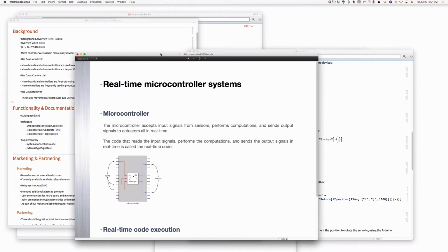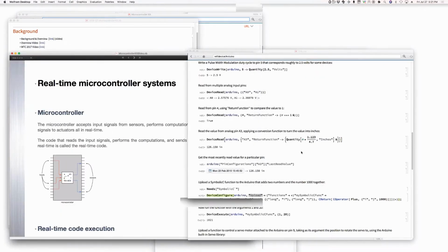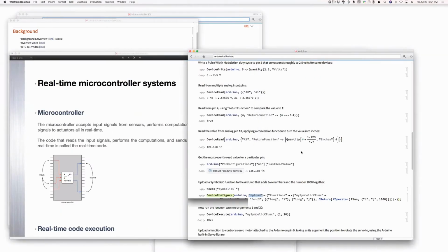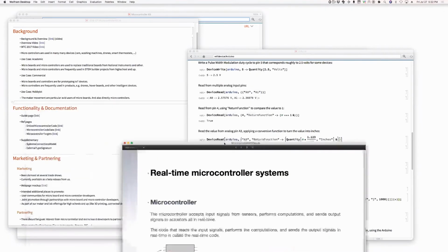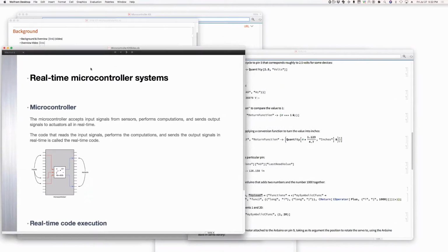So that's the other difference between this one and Arduino Link. You can do that workflow that exists in Arduino Link because we can connect to an Arduino. An Arduino has two things: a bootloader on the chip, and a USB to serial converter. Not every microcontroller has that; a bare metal microcontroller doesn't. So in the general case, we have what's called the hardware programmer. Again, it's in that workflow diagram. No, I understand, but I want to see it in the case that you've.